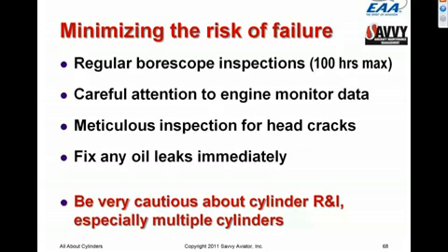Every cylinder head is going to crack eventually. If you're lucky, it'll crack between the top spark plug and the injector, and nothing terrible will happen. But if you're unlucky and it decides to crack at the head-to-barrel junction, that can really ruin your whole day. So we need to inspect cylinders very, very carefully for head cracks.